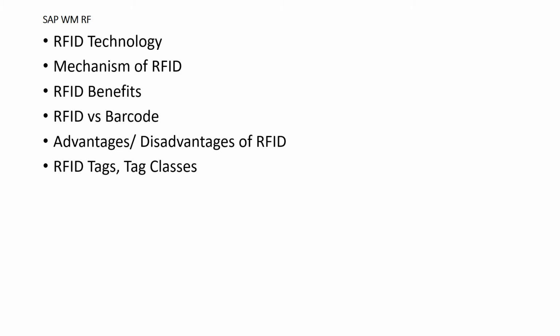RFID signals can encounter problems when being read through some materials, such as metals and liquids. Tag placement is of greater importance for some materials in particular kinds of containers, crates, or shrink-wrapped pallets. Some case-level RFID tags have to be placed in a specific location on the case, and cases must be stacked in a specific orientation or configuration to obtain a consistent read from the RFID tag.